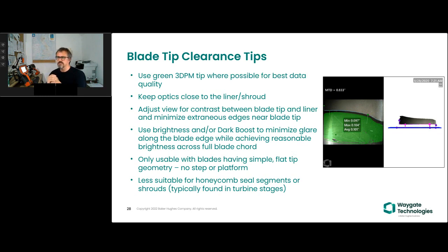What we also have, if you were to press the image soft key on the borescope, you enter this page called the image transforms page. So you can adjust the brightness. You can also adjust the setting called dark boost that improves the clarity and the appearance of the overall scene, just in case perhaps the trailing edge or the far field surface of the aerofoil is dark, or too dark, for instance. So just to improve and optimize that scene.